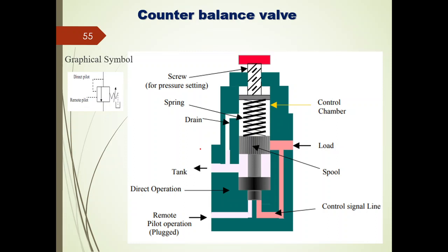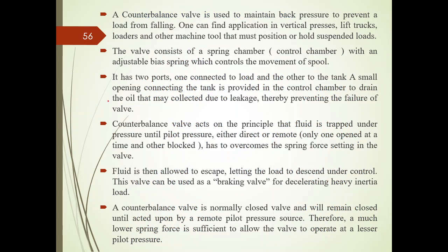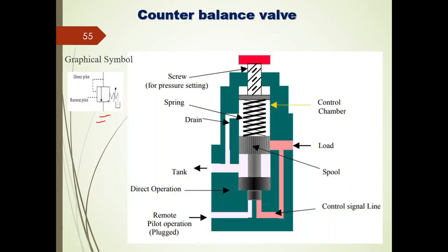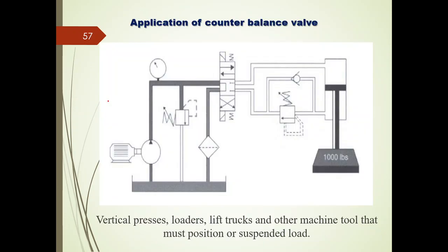So the next one is the counterbalance valve. This is the graphical symbol representing the counterbalance valve. The counterbalance valve is used in order to control the free falling of the vertical load. So we can discuss it here with the help of this diagram.